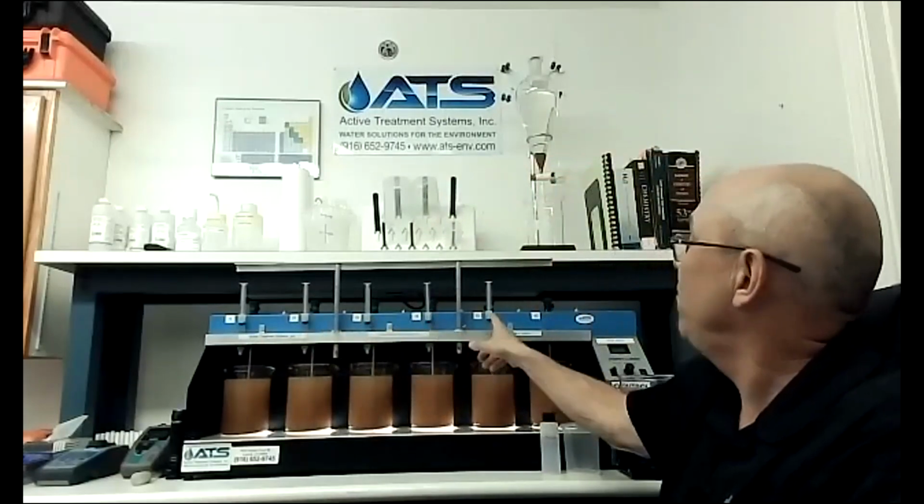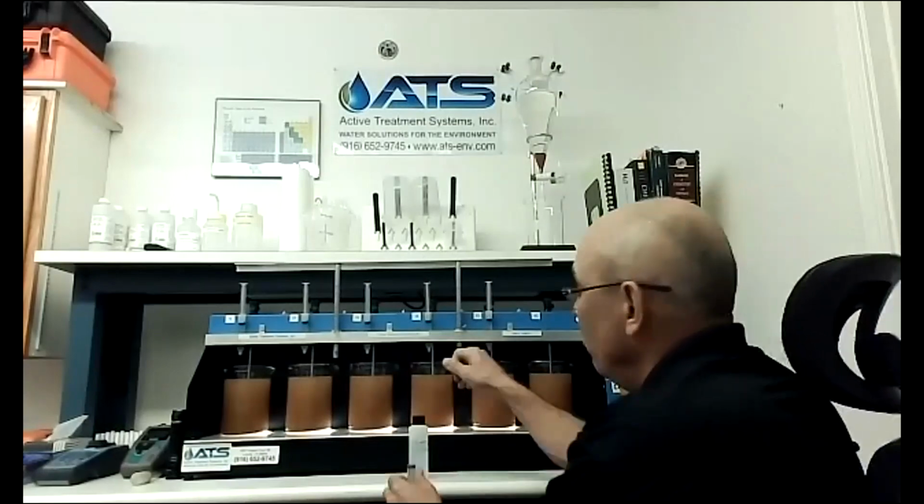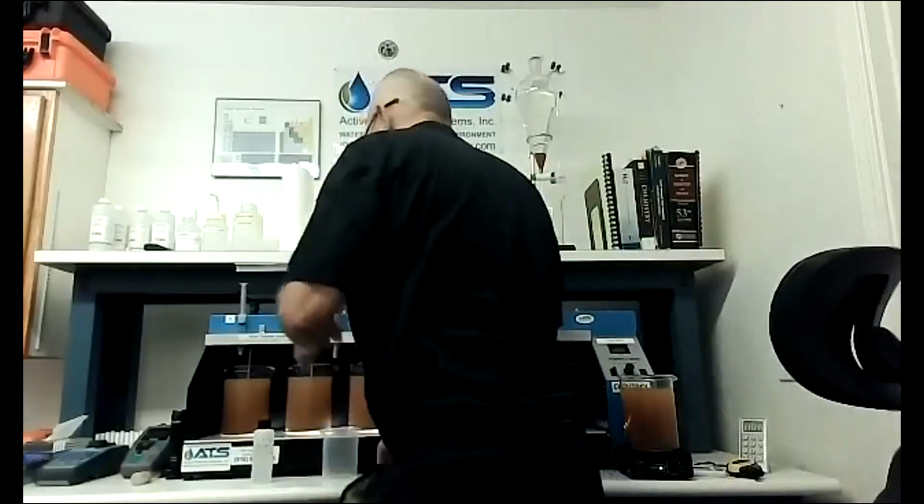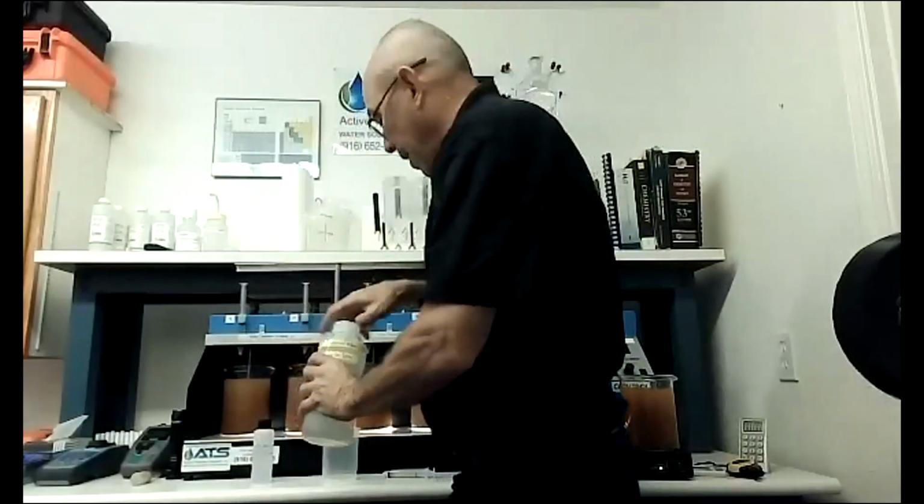Prepare different doses for each jar. So each of these injectors has a different dose. I'm going to go ahead and fill this one right now. I've done 100, 150 parts per million, 250, 350, 450, and I'm going to do 550 in this. The polymer I have is a 10% mixture where 1 milliliter equals 100 parts per million. So I'm going to go up to 5.5 milliliters in this, and I'm going to set that up and get ready to inject. I'm going to need a little bit of deionized water.